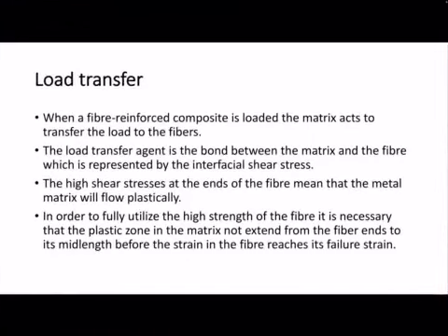Okay, so we want to look at the load transfer. This is now load being transferred from the matrix or the resin to the fiber itself. So when a fiber reinforced composite is loaded, the matrix acts to transfer the load to the fibers. Because if you think of a composite, let's say that's your component. Of course, the fibers are going to sit inside the composite like this, and